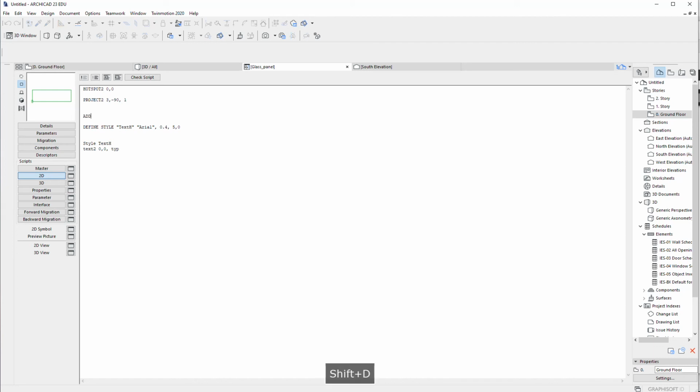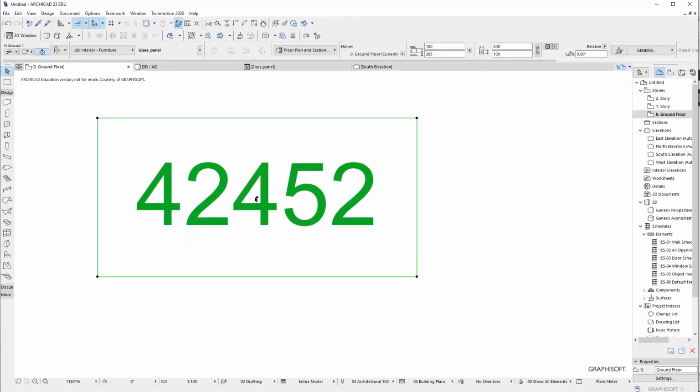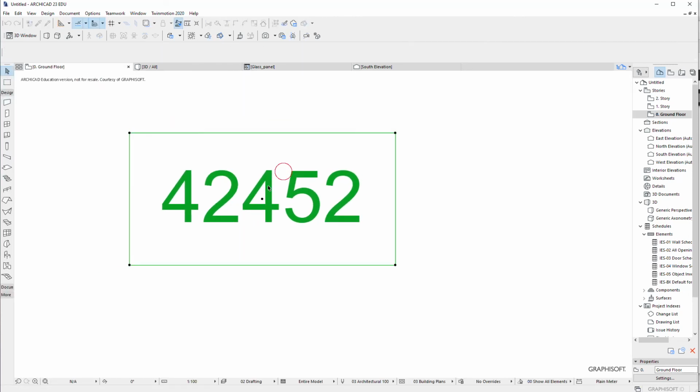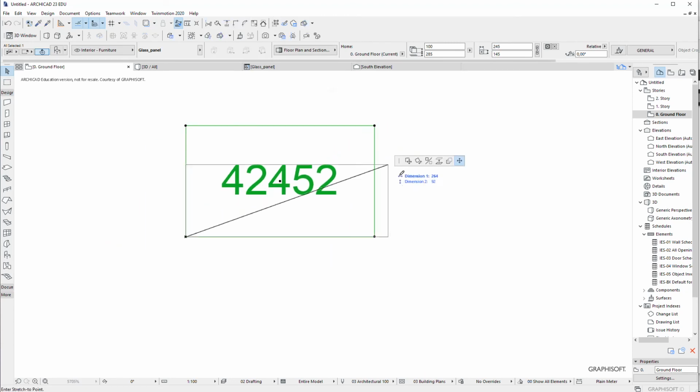So add is like moving the whole coordination point to somewhere else. So we'll move it from this area to half of the width and half of the length on both x and y. So we start by ADD2, and we'll say add the x, it's the a divided by 2, and the b divided by 2. Now if I save it and go here, see now it's the middle. Now the whole text is going to the middle. I have my points here at the corners.